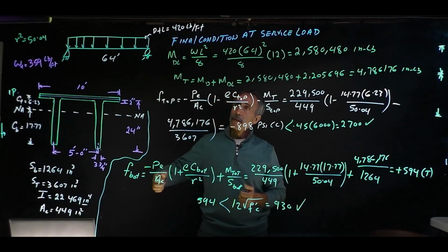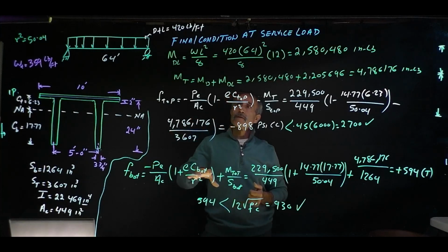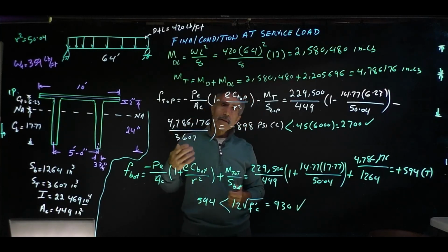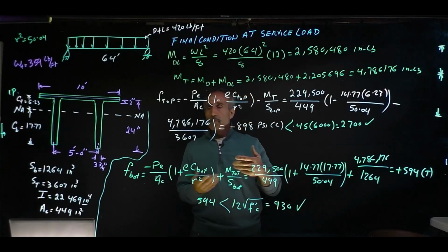See how we check the stress at the bottom and the top of the pre-stressed beam after being cured at the supplier yard. So before its losses and after the losses at this final service load, we check like that.